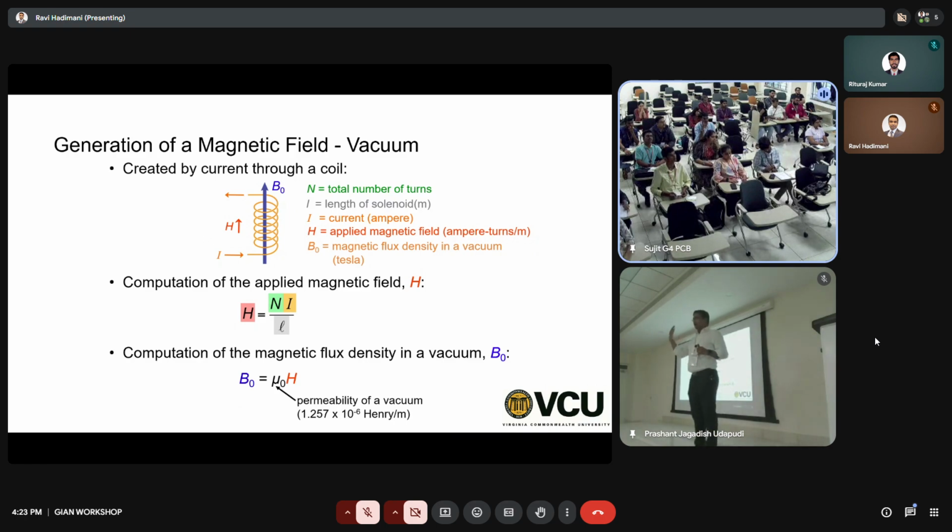So how current is important in generating the magnetic field, likewise B is important in generating the after effects of the magnetic field, which is induction heating or generating torque in motors. That depends on B, which means you have to choose the right material. If you choose the material that doesn't respond to magnetic field, it's useless. You can't get heating, you can't get torque, right?